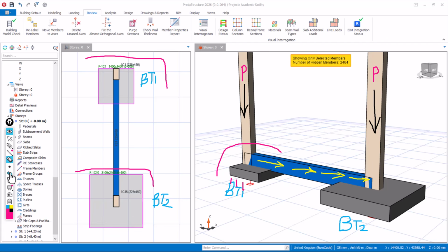Now, knowing that it is practically impossible during design to make this column at one side, which is an eccentric column, overturning free, because when it comes to the E, which is the eccentricity, the E must be less than B over 6.